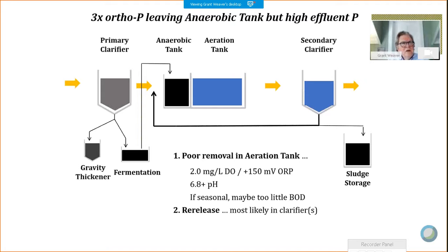there's a Little Mouse Creek, which is an oxidation ditch facility. In the summertime months, they're seeing really low phosphorus concentrations going into the secondary clarifier, 0.2 kind of numbers, but coming out of the clarifier was over 1. More than 1 on days this was observed.